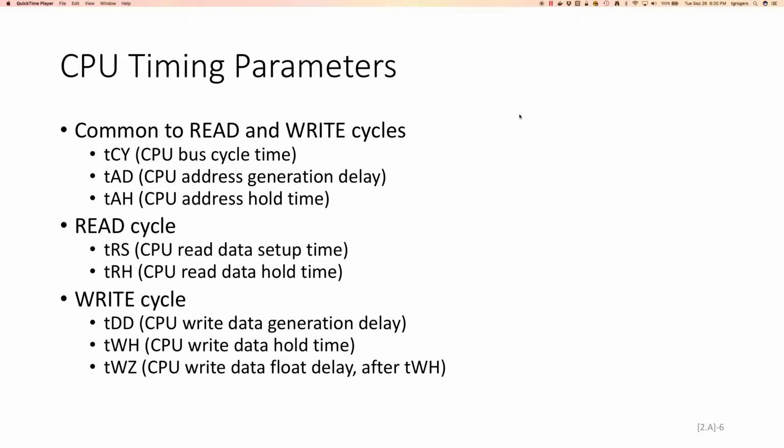Read cycle has some specific timing parameters, setup and hold time in particular. And on the write cycles, there are some timing parameters associated with when the CPU is able to put the data on the bus, which is TDD, how long it's held, and how long it takes for the float delay to take place. So what's most important to keep in mind when we go through all of these exercises is that we're just trying to create a system where the data does not violate setup and hold times.